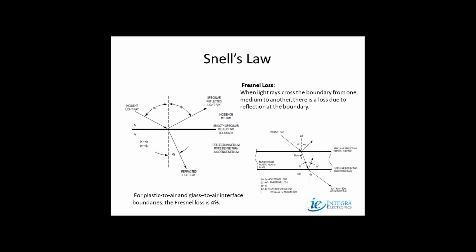The two things that are important to remember are, one, there's a critical angle that the light hitting the boundary has to be beyond, which in glass and plastic is typically about 49 degrees away from the vertical. So as long as the light's hitting from 50, 60, 70 degrees off axis, the light will reflect back into the pipe. The second thing to keep in mind is this only works when what's outside of the light pipe is air or vacuum or some other kind of gas. If your light pipe is going to be immersed in water, it's not going to work at all because the light will simply go right on through. And that's pretty much it.